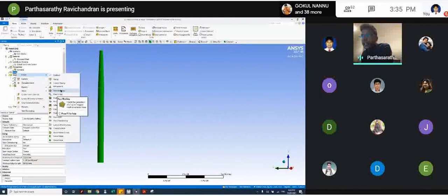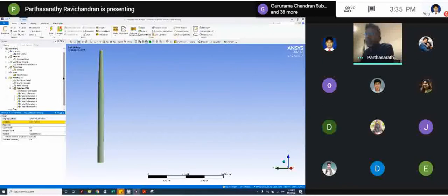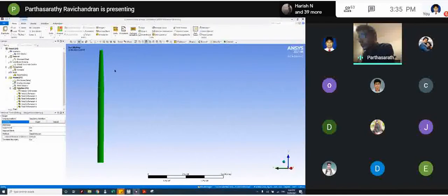But since it is a surface model, we can directly use the face meshing option here. The moment it asks what to consider, we put the surfaces in. In this case, it is two faces because there is a problem with the geometry, but in an actual case, you will have shells for each surface, so you consider the whole geometry.